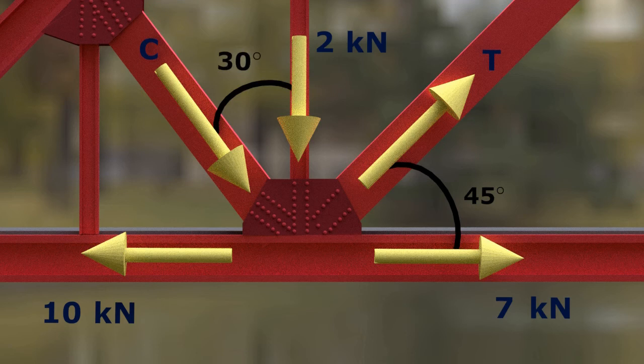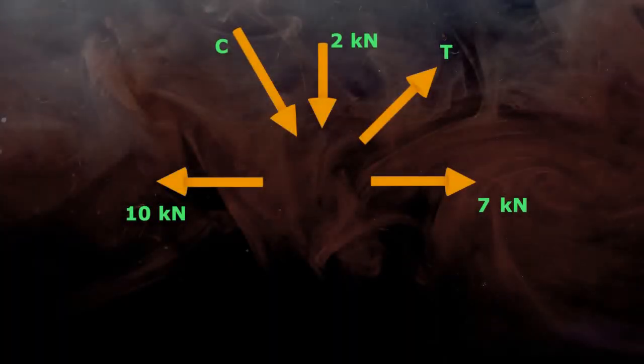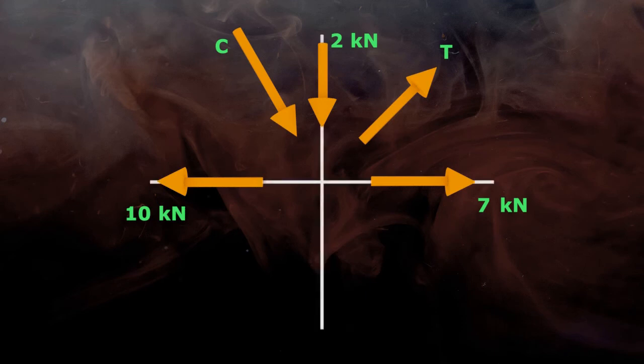As there is no direct external support to the joint, like there is no direct contact to any pier or wall, which means that no adjacent body is directly supporting this particular joint. So only the forces acting on the joints of connecting members will be included in free body diagram. So this is the free body diagram with all the forces along x and y axis.